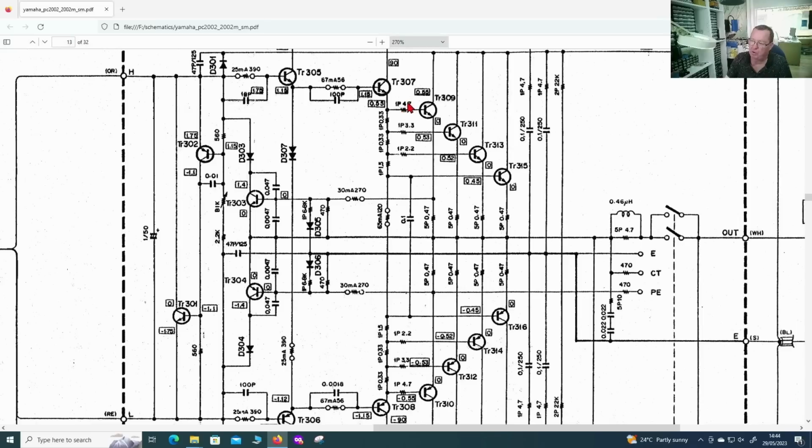You don't want it to go up to half a volt to switch the thing on first. Otherwise, you'd lose a chunk out of the middle of the sine wave when it's near to 0. So that's 0.55. Then look, we have a resistor, 0.33 and 3.3, different values. And this has 0.53, so this transistor is not as turned on as that one.